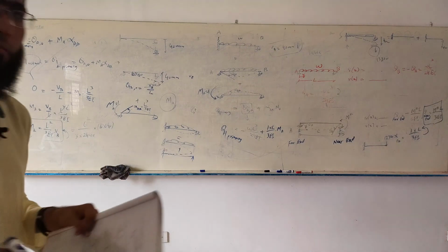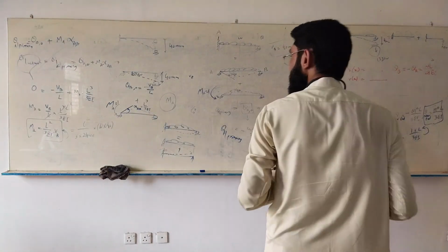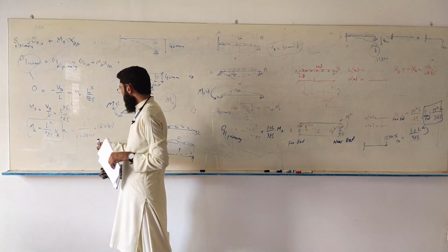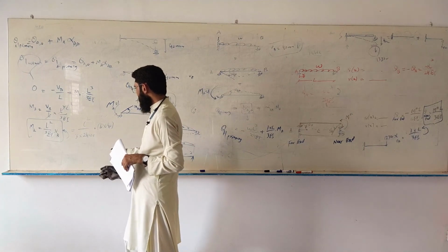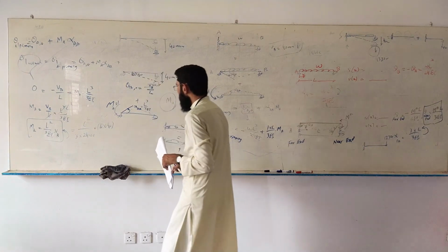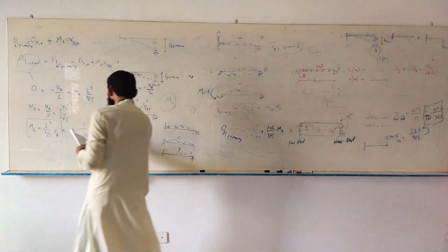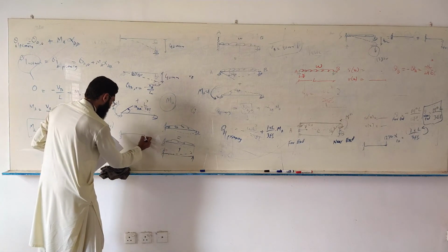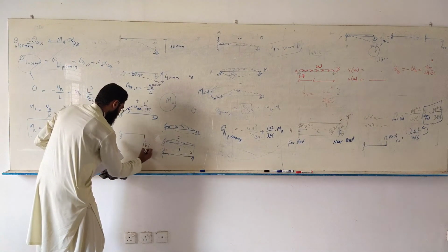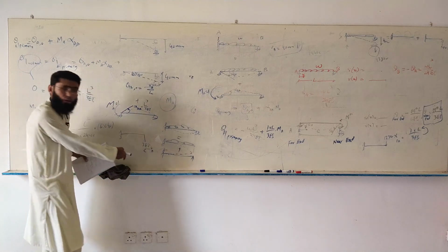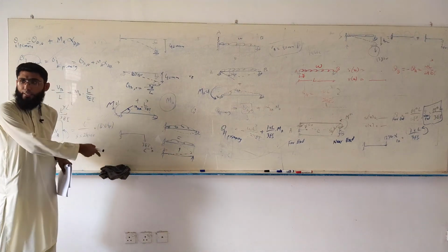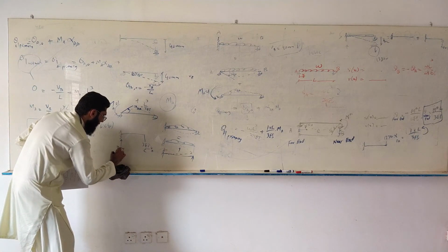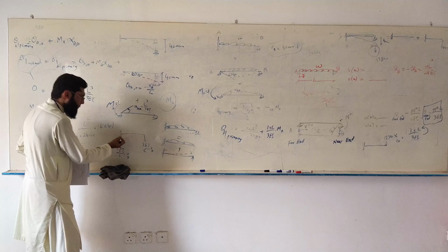2 multiplied by 10 to the power 5? Really? This is 6 squared. Am I doing anything wrong? Last time, for case number 2, we got this answer, so this should be 3EI over L cubed times VB, same magnitude but opposite direction.